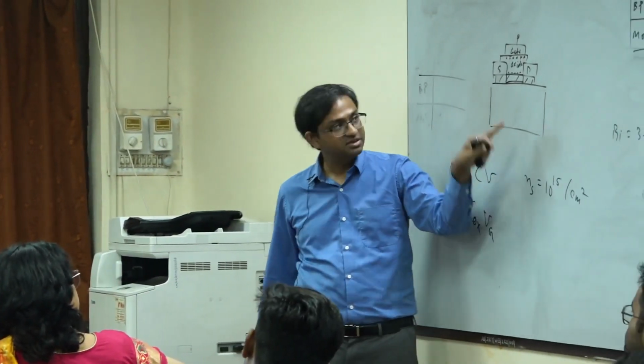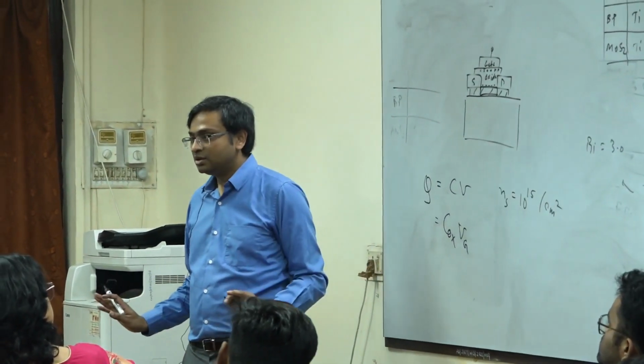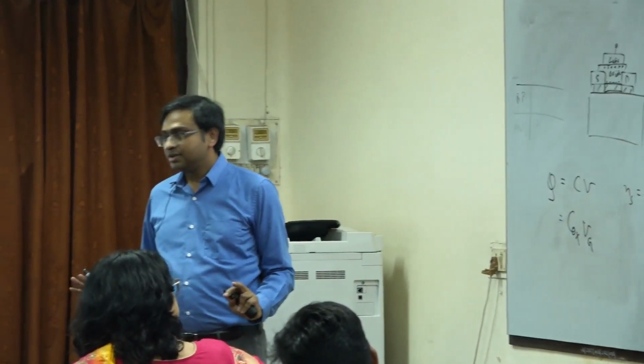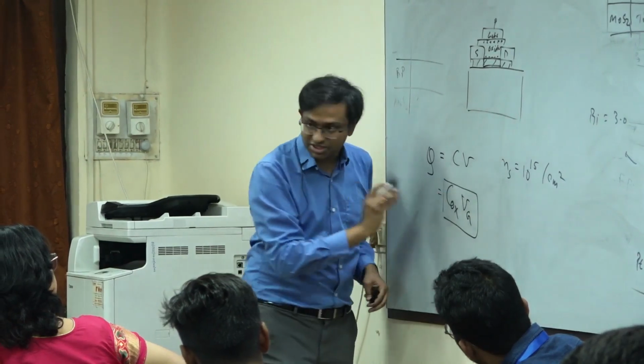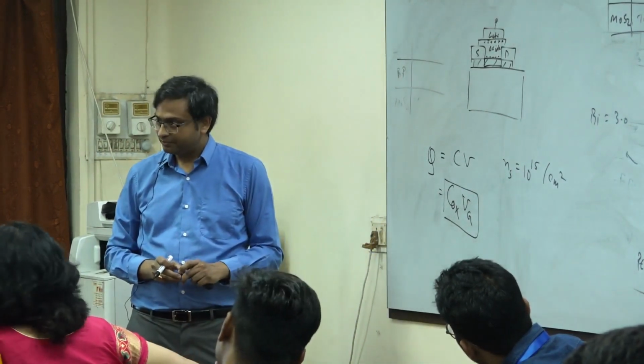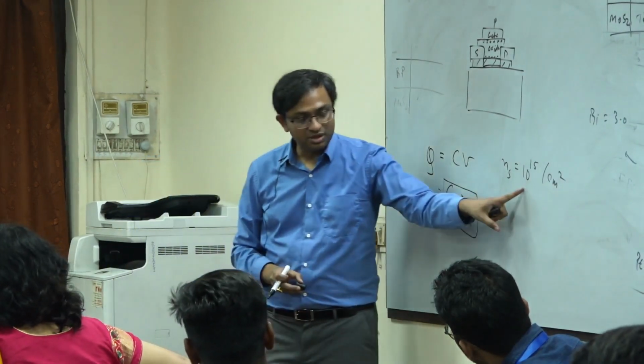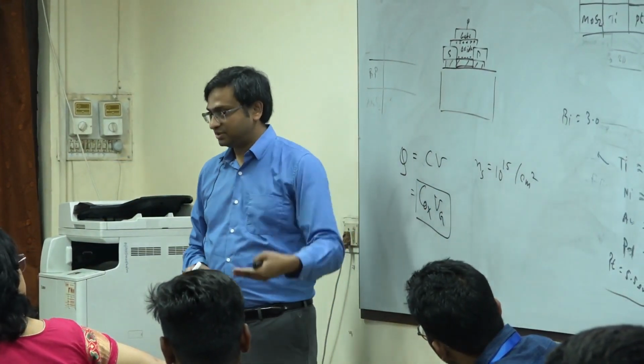So this is something we call degenerate doping, correct? So this much charge is already there in the channel, and the channel conducts. So if I want to turn it off, I need to get rid of these charges, right? Because this transistor is right now on, because there are a lot of carriers. If I want to make it a transistor, I have to be able to switch it off, right? So I need to make sure that my gate can provide an equal amount of opposite charges, right? Okay. So this is the amount of charge the gate has to reverse.